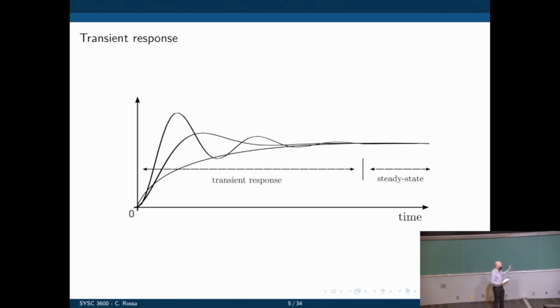So to be able to properly control systems like that, we need to pay attention to two things: the steady state and the transient periods. We covered both of them. For the steady state, we can use the final value, and the transient, we saw how to characterize it in the last lecture. It depends on the damping ratio, and depending on the damping ratio, we can go from exponential waveforms to combinations of exponential and sinusoidal waveforms. We can even have systems that oscillate and never settle, or systems that are unstable and whose output simply blows to infinity.